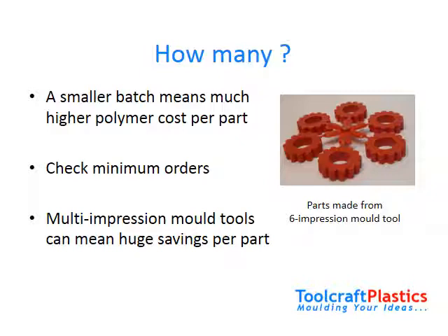If you obtained a quote for 10,000 mouldings to start with, your moulder may have priced for a multi-impression tool. Multi-impression mold tools can mean huge savings per part. There's a higher initial cost for the mold tool, but a much lower price per moulding. If you drop your quantity, a multi-impression tool may no longer be cost effective and the price per part will go up. If you expect low quantities at first, but good sales growth later on, it may be worth having the tool made with some so-called blanks, so that it can be turned into a multi-impression tool later on.